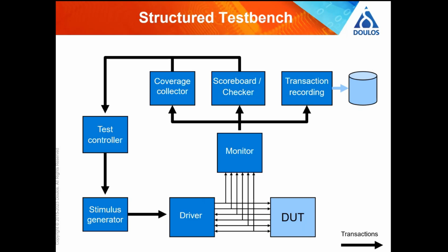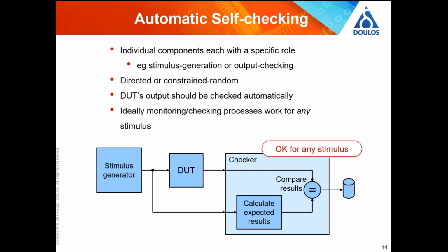So one of the key difficulties, one of the key jobs that your test bench already has to do, which I've already talked about, is checking. So how do you write a checker? And this is like the $64,000 question, because it's not easy, frankly. It might be easy. It depends on the design you're dealing with. If you have a garbage in, garbage out sort of design where you put something in one end and the same thing comes out at the other end, reasonably easy to check, but that probably isn't the case.